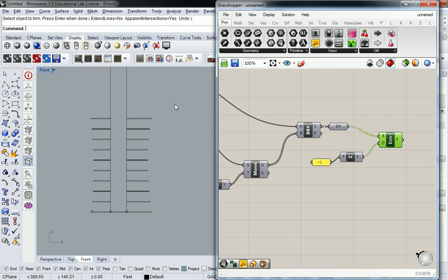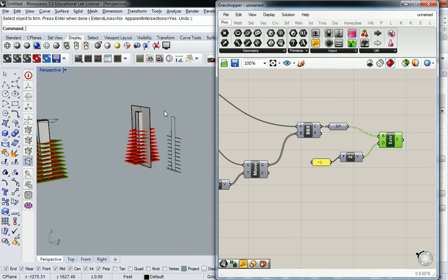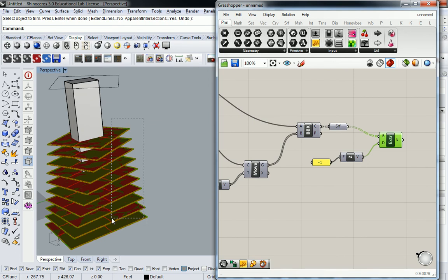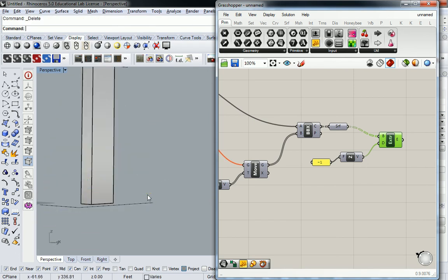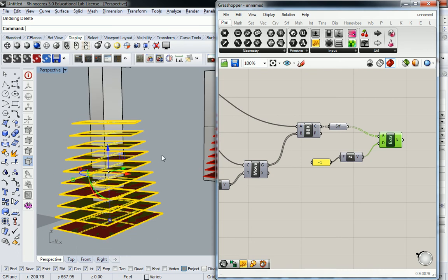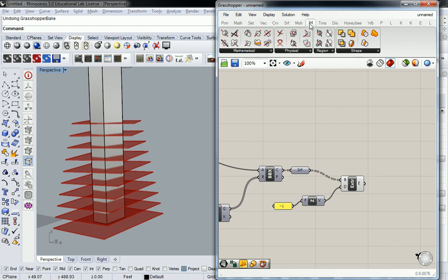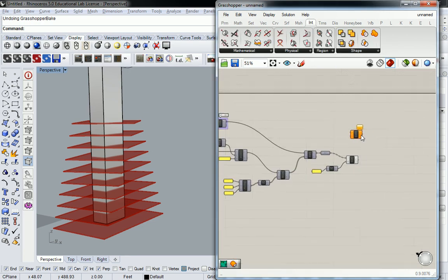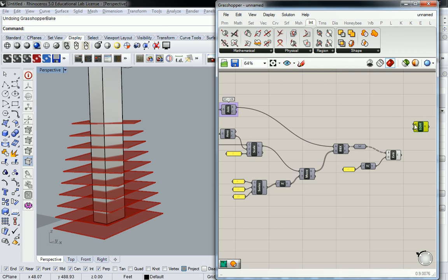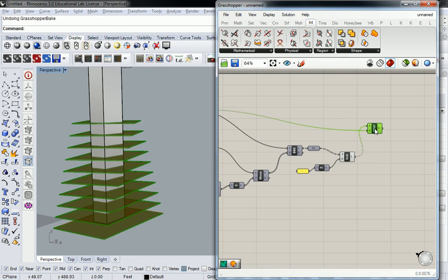And it's as simple as, go back to perspective here. Actually, let me get rid of those. Oh, whoops. Oh, shoot. Hang on. There we go. And it's as simple as just a subtraction. So I'm going to go to Intersect, Shape, Solid Difference, and I'm going to, I don't know, let's see. The item you want to subtract from, and then the item you want to subtract with. So that would be these, and then this one should go in there. I think that's the right way. I might have done it backwards.